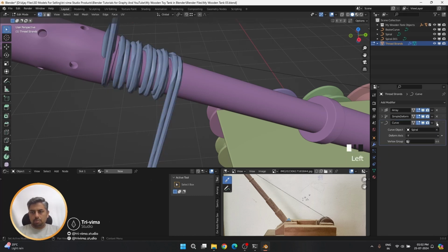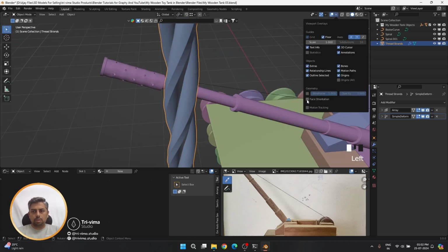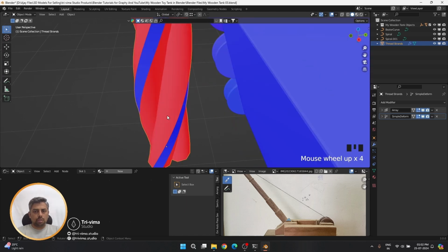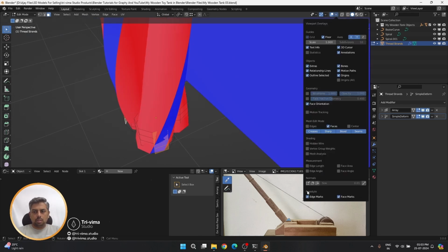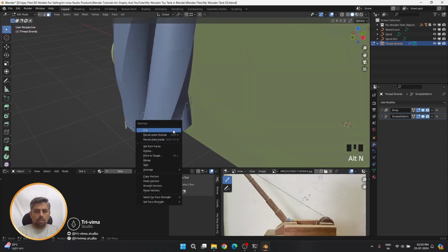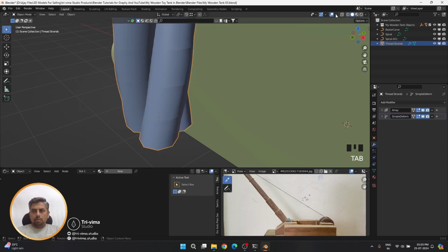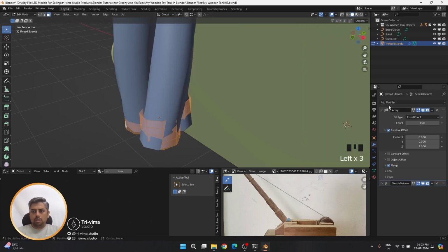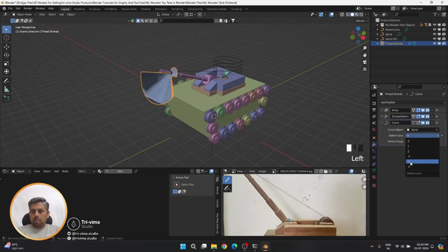I will remove this, I'll remove the curve, and then select all. Let's check the orientation, face orientation. Okay, see, this is the issue. That's why it was not so perfect. So what we can do, let's change this. Okay, and select all, positive. Now let's change it. Go to array, merge it, and then now we can do curve, click, and this.